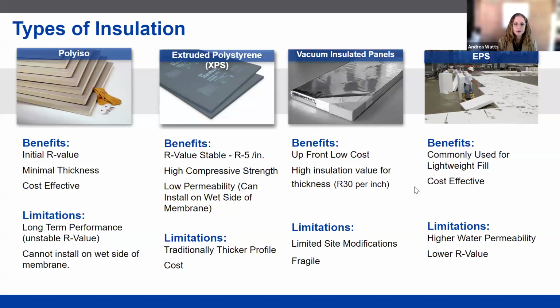Because of that, we have to protect them, typically using some sort of polystyrene, typically XPS. We use the XPS around non-square areas, around penetrations, protecting the top and bottom of the panel. So there is a craftsmanship into how we lay out these panels to do it effectively.